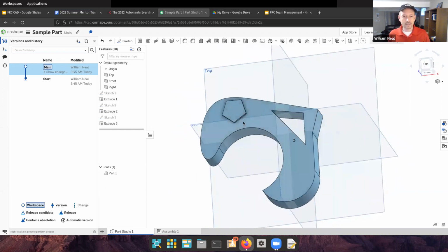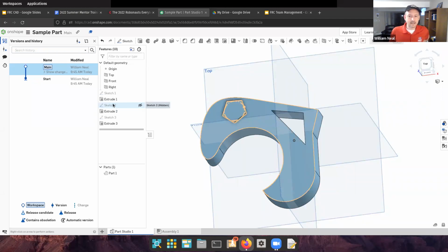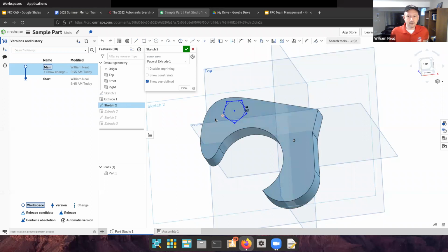And all the while, I can constrain anything that I have done. For example, this, I didn't specify any dimensions. Well, I can go back to my sketch of this feature here, and let's put a dimension on this part right here. So at the moment, that's 13. Let's make that 15. See what happens. There, it's still inside my shape. I could even make it bigger and it will come right out the side. That's okay. It will still be working like that.